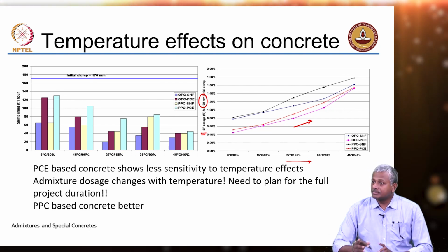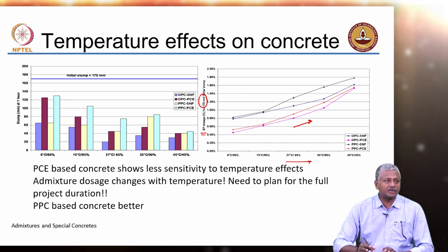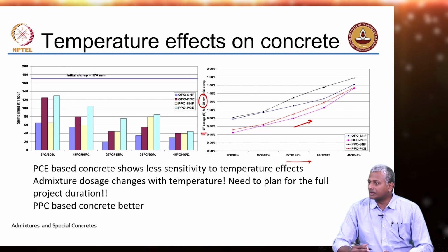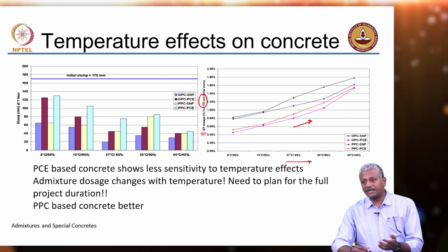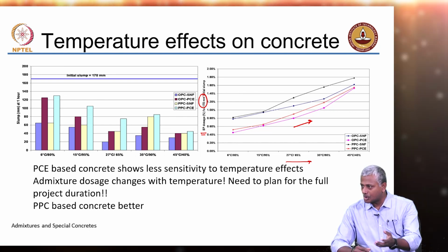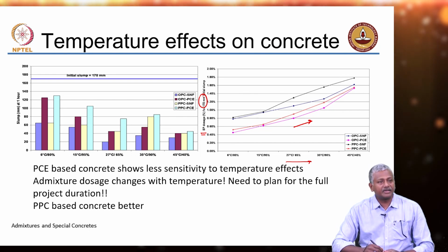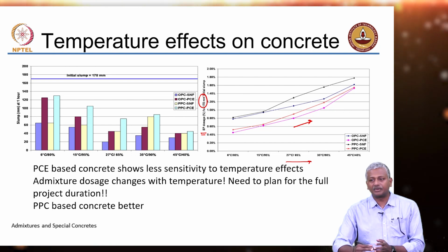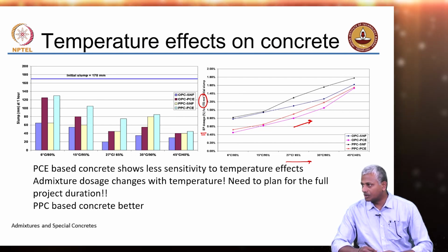See here there is a little bit of a difference when you consider a paste system versus a concrete system. In the paste system we understood that as temperature increases, because of increased adsorption you may actually get very high initial workability. But here, yes, maybe you do get that workability, but you need a higher dosage to get there.